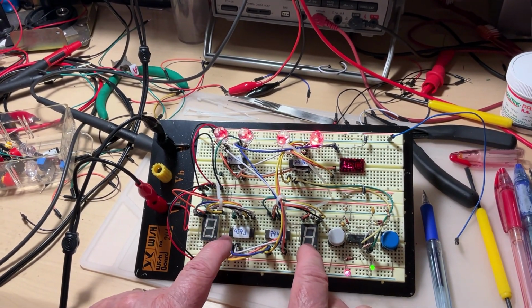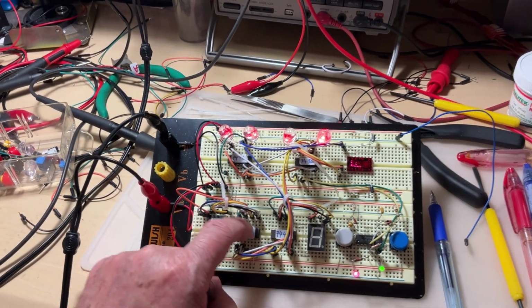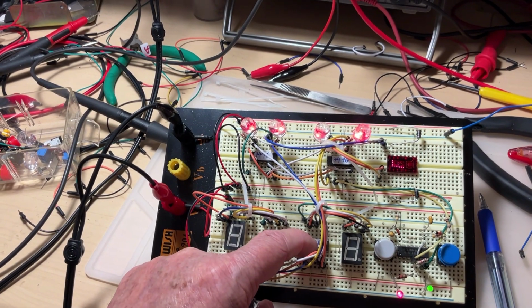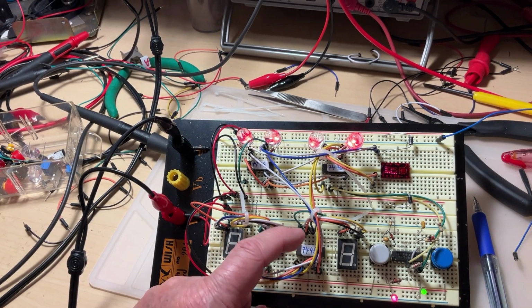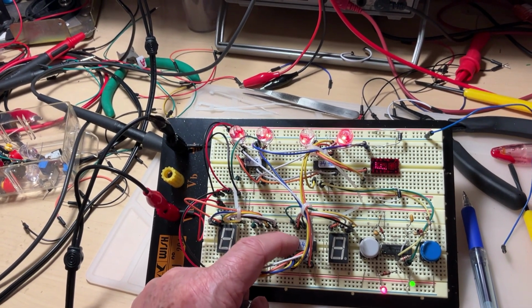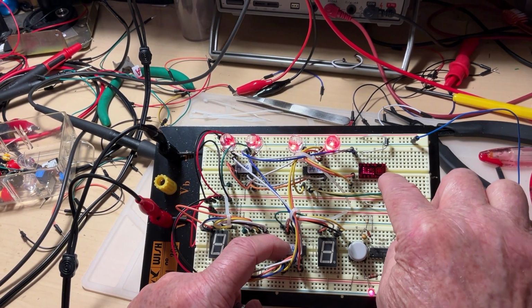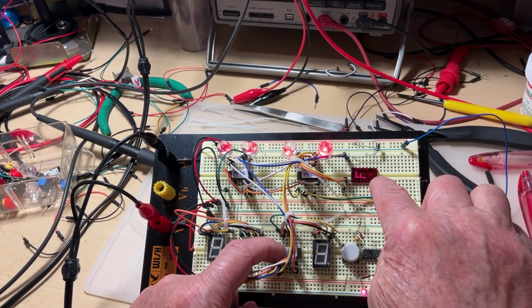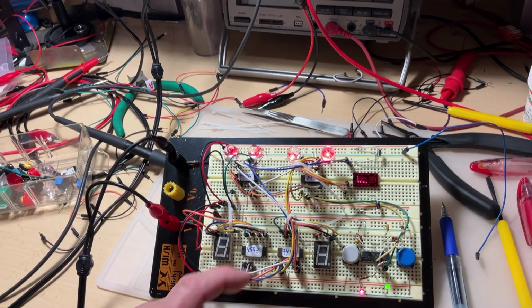And now you can understand the difference between the three kinds of displays, because it doesn't matter the displays, what matters are the decoders. Here we have a BCD decoder inside. Here we have a hexadecimal decoder, but it is not capable of displaying the actual letters, this one. It only displays some symbols. And this is a full hexadecimal display where all the letters A, B, C, D, E, F are going to be shown uppercase, okay?